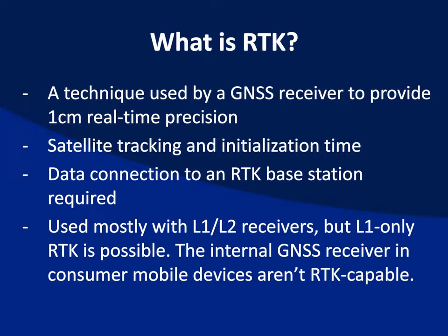And so RTK is used mostly with L1 and L2 receivers, which are commonly referred to as dual frequency receivers. It used to be GPS only, but nowadays a lot of them are GPS and the Russian GLONASS system, because it adds more satellites. And if we go back up to number 2 on this list, the more satellites, the better.